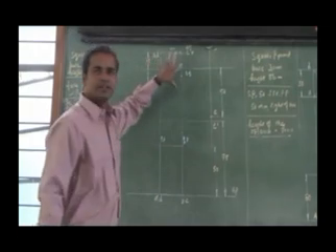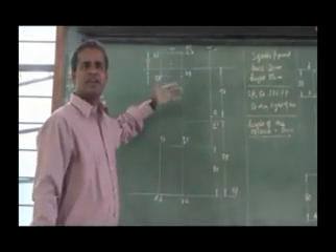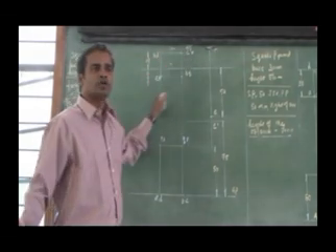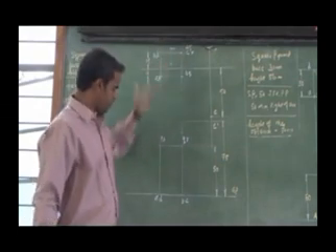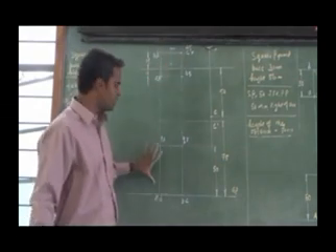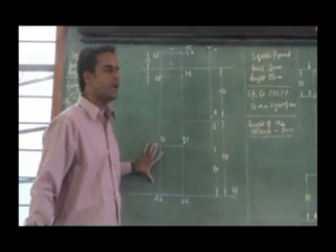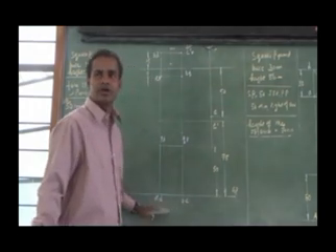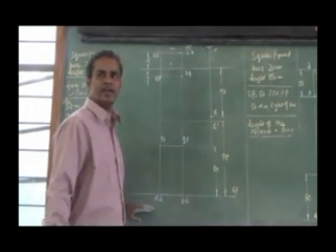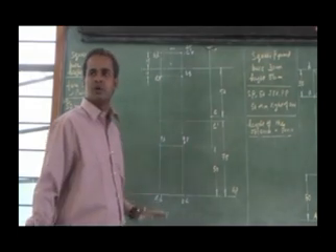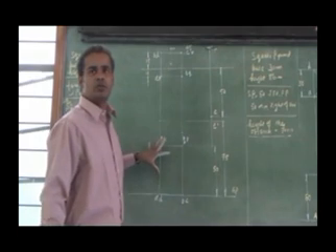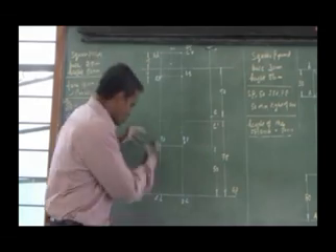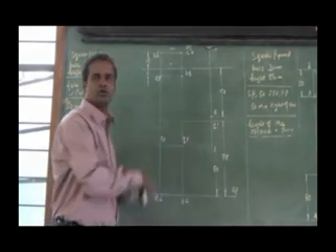Drawing the layout, it is kept vertically, the face is parallel, and the face is 10 mm in front of the picture plane. You have to draw the top view as a square. Then the front view will be a rectangle for the height 50, straight away projected. Then you leave a gap for the ground plane. Don't draw the ground plane to the bottom, similar to the previous problem. Since the perspective view for this in-front portion will be bigger in size, I need a space below the ground plane. That's why I am leaving a gap.